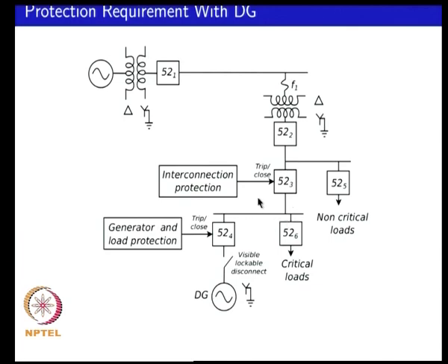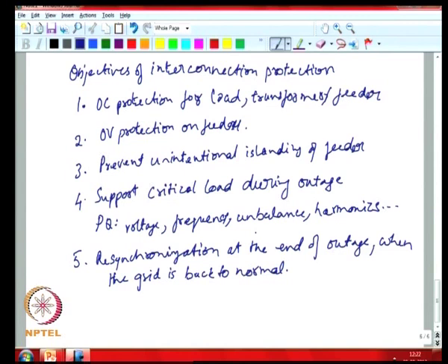If everything is dead, you can re-energize your critical loads, as long as you are not re-energizing a connected DG. You do not want to start up a large machine or an inverter when it is still connected and is not supposed to function, so you want to prevent that, but you want to re-energize a dead bus. So, dead bus restarting with the appropriate logic would also be required.